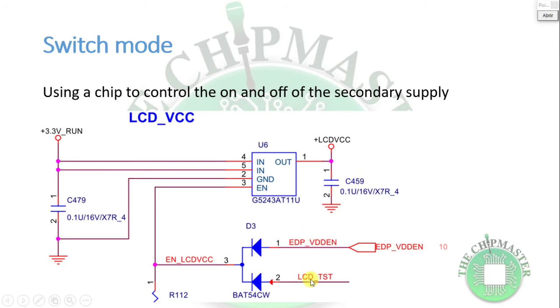So any one of these two signals has high level, right? Any one of these two signals. This is a diode D3, which is an OR application of a diode, indicating that any voltage coming on either side. This is known as an OR. You can use an OR gate, right? So this is an OR application of a diode, using a diode as an OR gate.